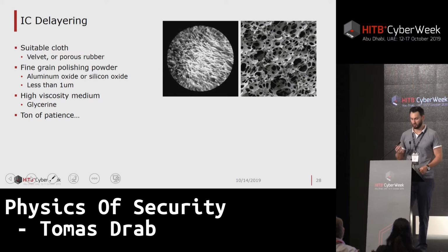You just need proper grinding material, put the chip on your finger and grind, and it just takes a lot of time, a lot of patience. You also will destroy some of the chips, but eventually you will learn the skill, and then you will be able to delayer basically any chip.